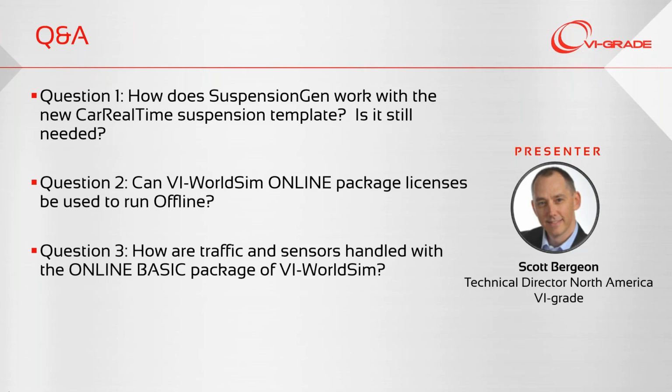Well, first, when tracks are created for WorldSim, there are two pieces to them. There's the graphic environment that's useful on the simulator, and then there's the road file that is used to interface with the tires. And of course, the road files are there, so you can run car real time offline on those same road files and be able to do offline analysis. And then when you switch to online analysis on whatever level of simulator you have, it's there. So I think the answer is yes.